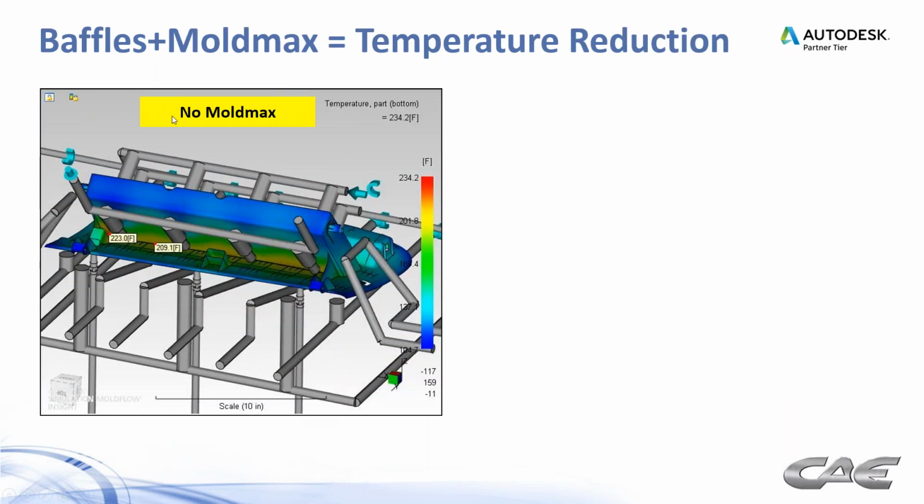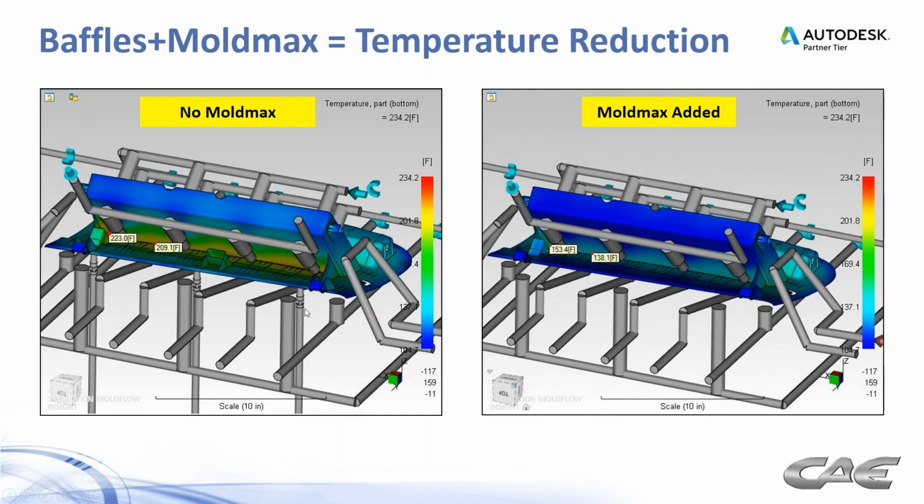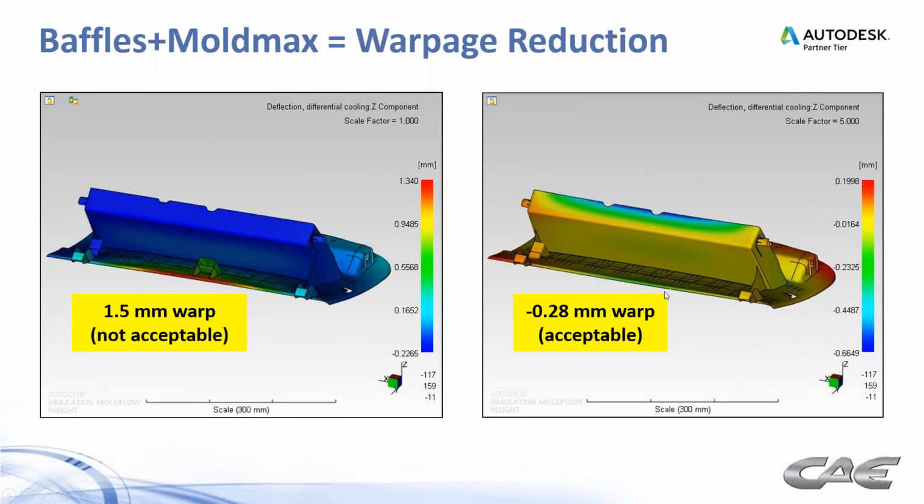In this case, without the MoldMax and with the baffles, same as the previous slide, now we are able to drop the temperature some 70 degrees in this area and same in this area. So not only were the baffles good for us, but the MoldMax inserts were as well. So very beneficial to add both the baffles and the MoldMax.